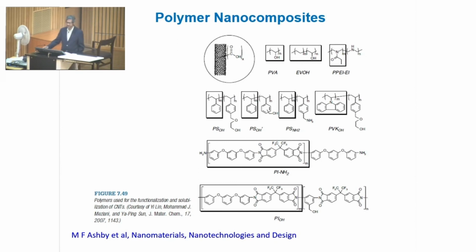Applications of the magnetic field or electric field have also been used to produce CNT alignment. It is observed that the elastic modulus measured in the direction parallel to the magnetic field was far greater than that perpendicular to the magnetic field. So, in fact, this suggests that alignment of CNTs contributes significantly to the increase in the mechanical properties of these polymer nanocomposites.